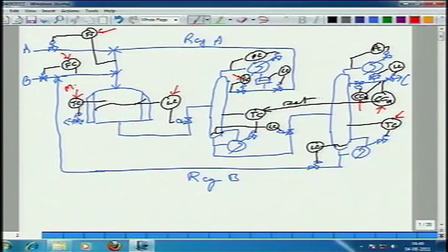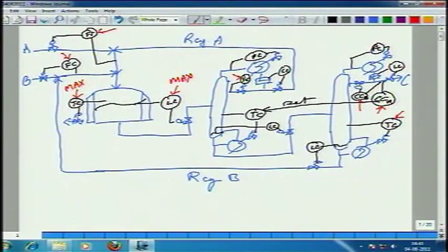This is a hypothetical example, we will make a real example just shortly, but I am just trying to walk you through simple rational arguments to figure out how to reasonably specify your 8 degrees of freedom, your 8 set points. Level of course should be max, because again that maximizes conversion and therefore minimizes the boil up. So, your steam consumption per kg product goes down.